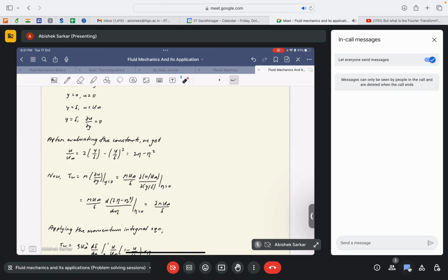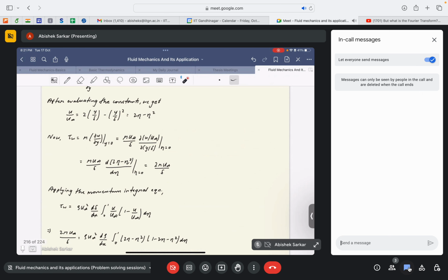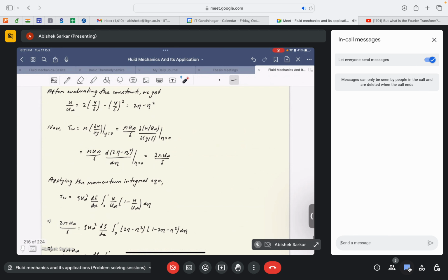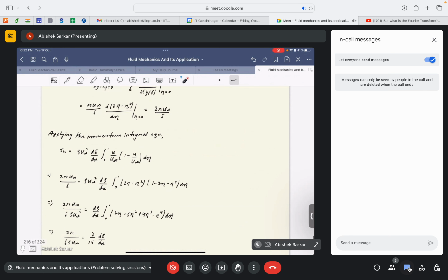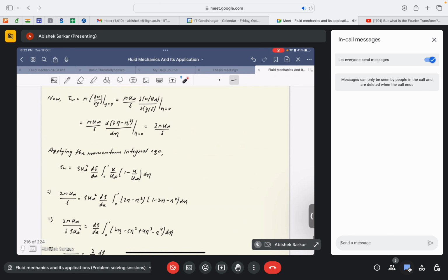Before that, we express tau in terms of delta, so that we can get an explicit expression for delta. If we know the form of the velocity profile, we substitute in the expression for tau 1 to get tau 1 equal to 3 mu u infinity by delta. You may ask, sir, since we know tau 1, can we evaluate it here itself? But the issue is that we don't know delta. In order to get tau 1, we have to evaluate delta first. That is the catch, and that's why I need to apply the von Karman solution.